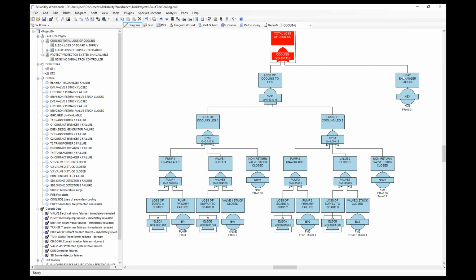The top event is created by combinations of basic events. These symbols down here are those basic events whose occurrence can lead in certain combinations to that top gate. The combinations are determined by the logic of the FaultTree. These gates that we have throughout the FaultTree, their symbol type indicates the combinations of faults that lead to that top event.